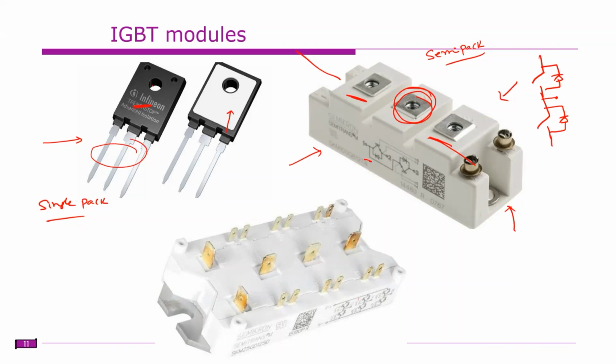Another good thing is that this is one phase leg. If you want some time delay between the two devices, inherent time delay is available. By using some logic circuits in the fabrication process itself, they will internally provide some time delay in the range of 1 or 2 microseconds.